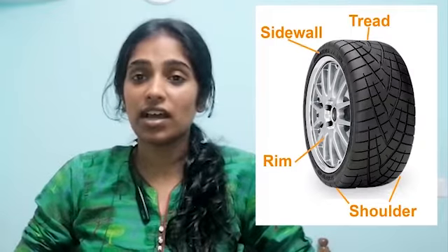Composition for different layers of the tire. Now the tire mainly consists of 3 layers. These 3 layers are made separately and then combined together, compressed and inflated to get the required shape of the tire. The tire now generated is known as the green tire, and it does not have any tread patterns on it. This tire is sent to a hot mold in order to shape it into the required shape and to transfer the tread patterns on top of it. Finally, the mold gives a finished tire and it is ready to be assembled.